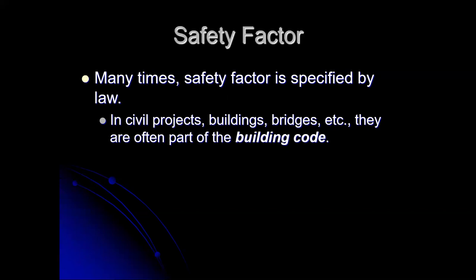We even have this in houses, in residential construction. We have the residential code, we have the international building code, and there are various safety factors built in there. They're not always obvious, because a lot of times they build into things like building code. They just tell you you need to span a certain width. Here's the minimum size 2x lumber you can use, made out of southern yellow pine. That builds in a safety factor because they know roughly what the strength of that material is going to be, and they figure out here's what you're going to need to span those walls, or to build a roof truss, or to build a header.